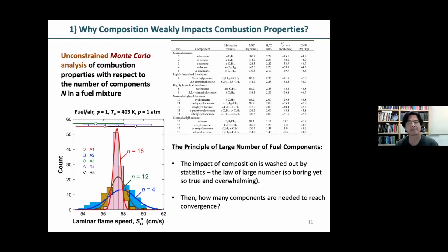So nature actually did us a great favor there. That is, it doesn't matter what you burn, large hydrocarbons will dissociate into a bunch of intermediates that have similar molecular weight as molecular oxygen. And that's why you don't run into a thermal diffusive instability problem.